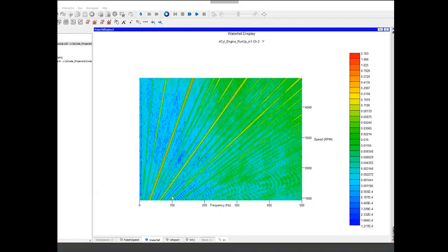That's my waterfall spectrum, and we see indeed those diagonals here, if you like, those lines. So I can track them using an order cursor. If you keep your mouse on this button here, you've got this order cursor. And if you look at the top left of the waterfall, you see a little yellow post-it. It says order 2. Then we move on to the next noticeable order, and that's order 4. Let's move on to the next one. That's 6, right? So now it's very nice.